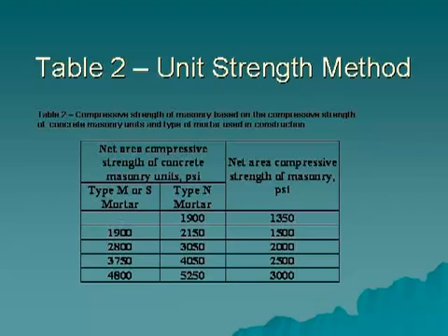ASTM C140 Section 5.2 contains requirements for testing block during construction for quality assurance. These are just minimum requirements. More tests can be directed by the purchaser according to ASTM C140. This is all part of the quality assurance and control requirements provided for in the code and specifications.